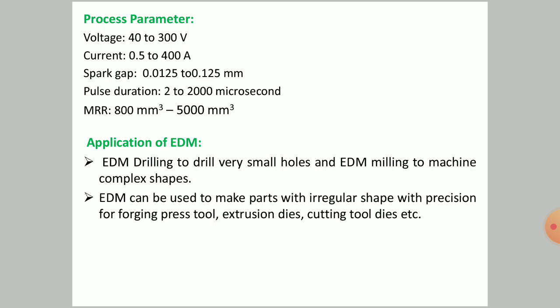The pulse duration is 2 to 2000 microseconds, and the material removal rate is 800 cubic millimeters to 1500 cubic millimeters. The applications of electro discharge machining.